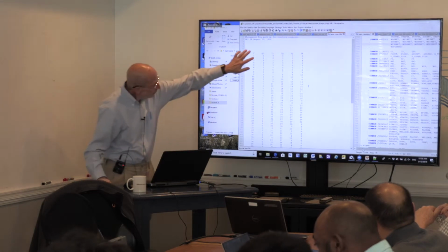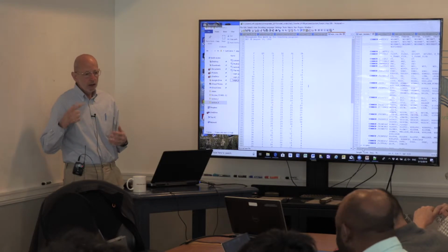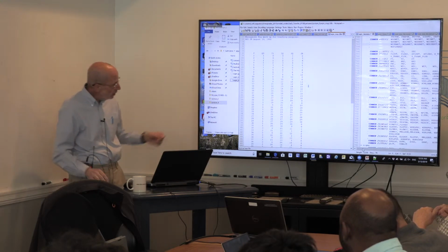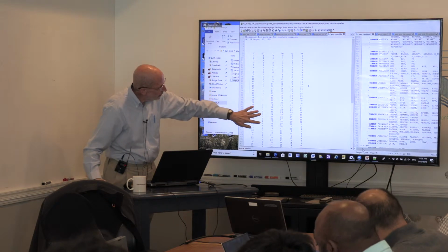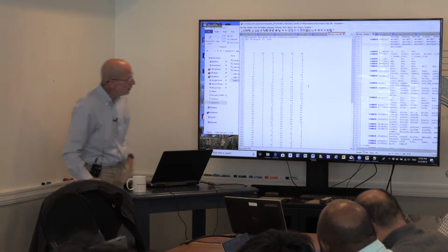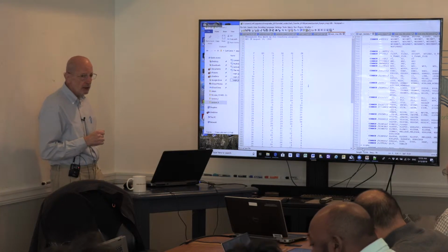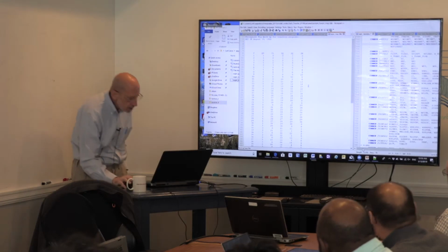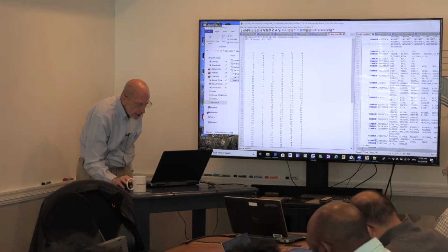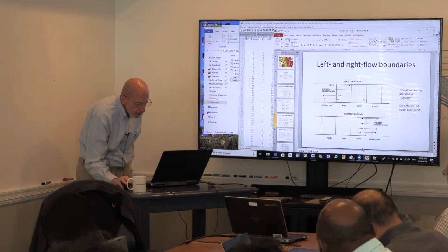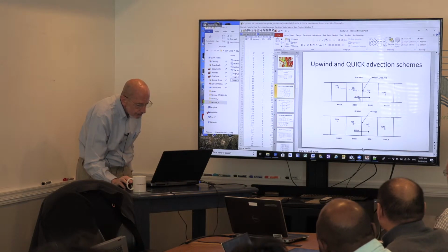You've got something called a flow direction. The flow directions are 1, 2, 3: longitudinal, lateral, and vertical. So this is a two-dimensional model, so you've only got either longitudinal flows or vertical flows. And here's the key, the things you need to look at. Remember what I said, for any face, actually I may want the one with QUICKEST for a moment. Let's look at QUICKEST for a minute.